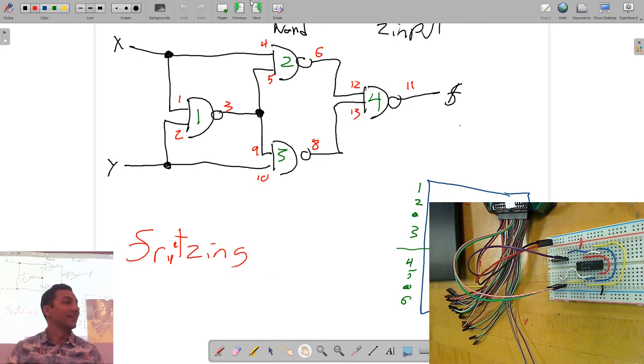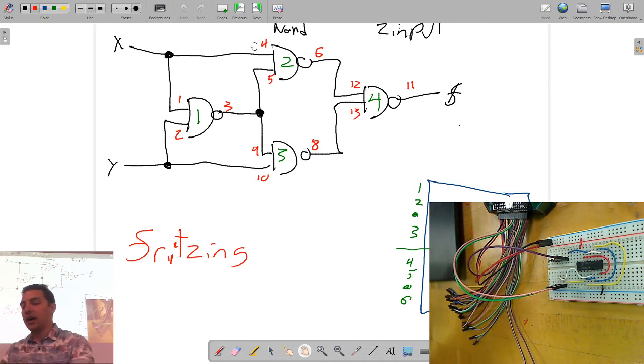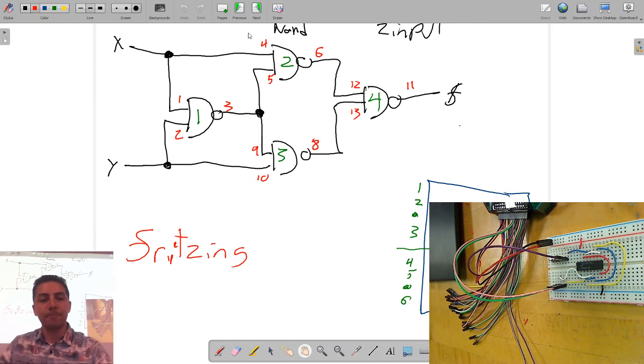No, you could, that's actually a valid point. You could leave them disconnected, which would be bad. On the list of common ECE260 problems is leaving an input unconnected. We'll get into why that is in class a little later, but yes, thank you, smart Alec. Leave it disconnected. Well, that's actually all of them. And all we just did there, I don't know if you noticed, was count in binary: 0, 0, 0, 1, 1, 0, 1, 1. And the Analog Discovery lets us do that.